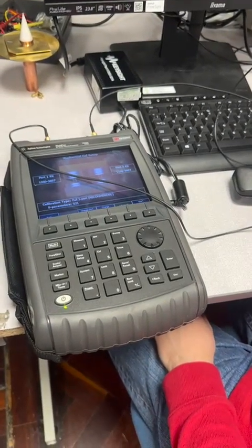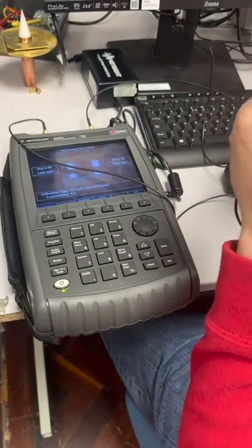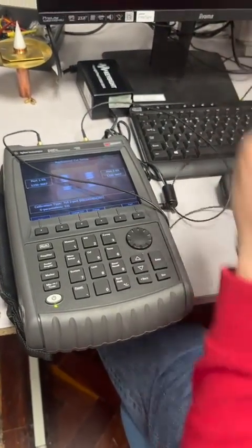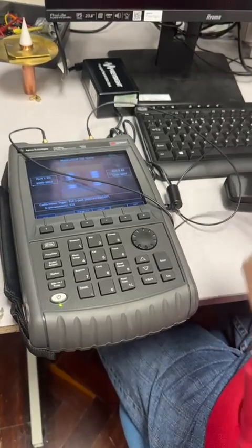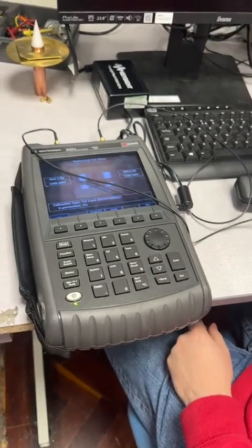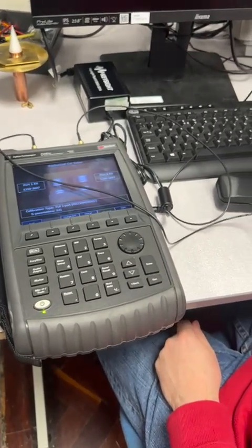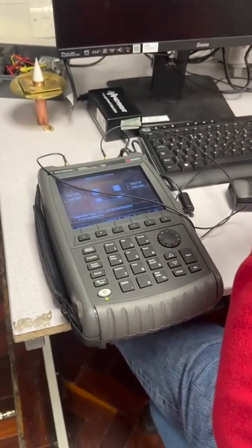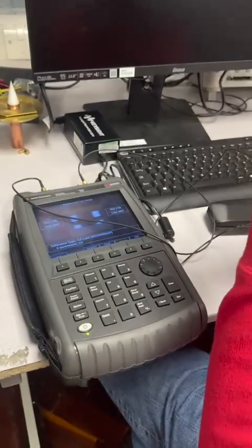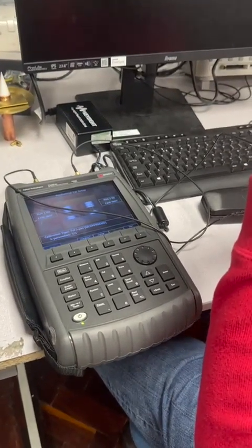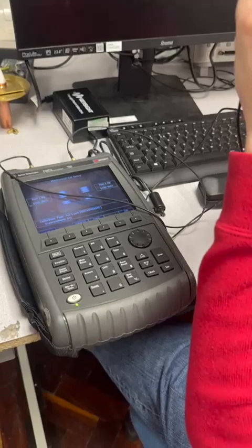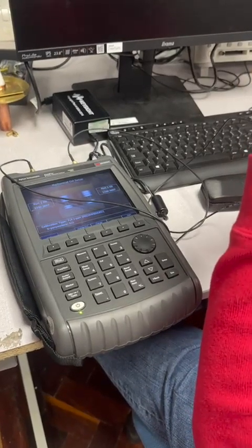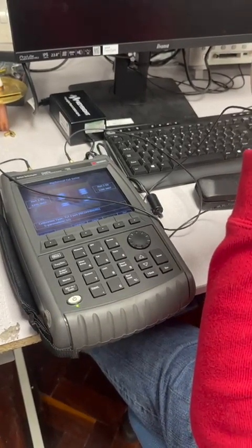Okay. So when you put the load that you've calibrated to on here, it will be perfectly down at infinity. Okay? In practice it isn't. It isn't really down at infinity. It's just because of that. It's said, right, I understand this cal, I know everything about this particular cal standard, and I'm doing everything referenced to that cal standard. Do you understand? So everything is actually referenced to the standards that you put on these interfaces.